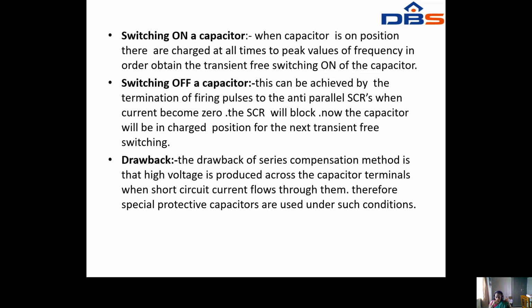Whenever we switch off the capacitor, this can be achieved by the termination of firing pulses to the anti-parallel SCRs. When the current becomes zero, the SCR will be blocked.